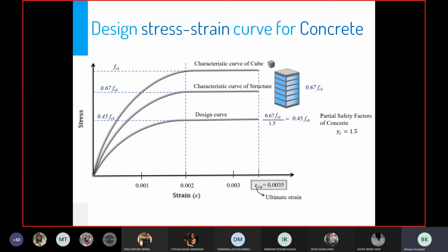The sort of batching that is done is volume batching, weight batching, and so on. So it's very approximate. The quantities of cement, water, coarse aggregate, and fine aggregate that they mix are very approximate. They have a general understanding that if I mix this, I'll get M20. In a majority of projects, there is no testing.